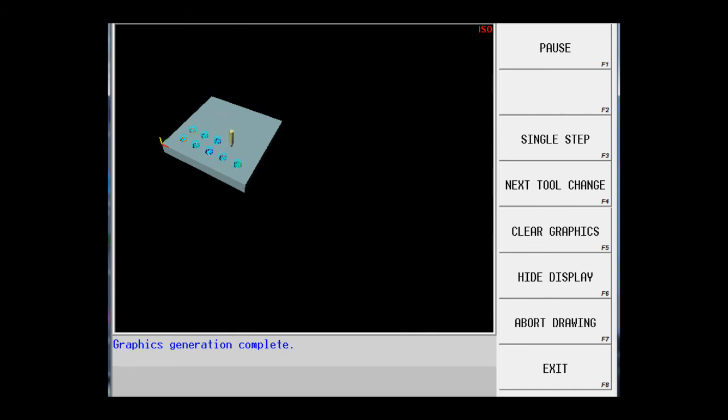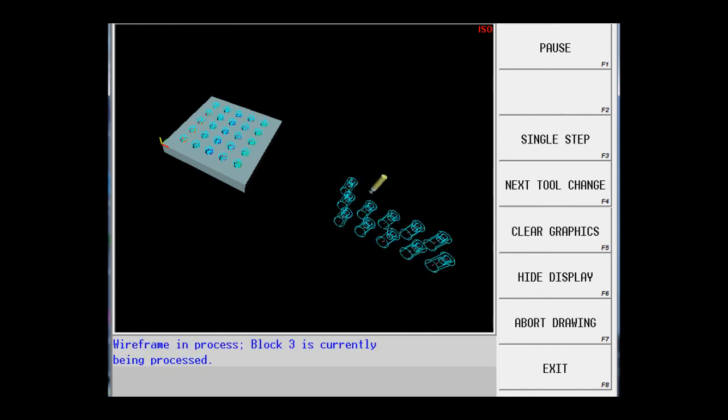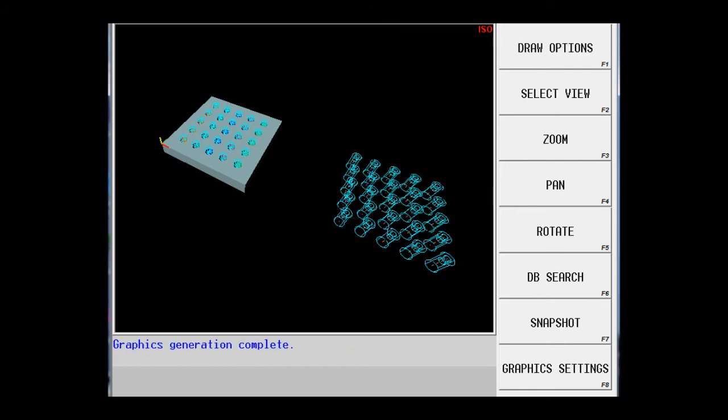I showed it to you in this manner only to show you that stock geometry does not pattern. There is no way for us to draw one small piece of stock and have that pattern with the geometry. So in this case, anything that was off of the solid model itself, when we were set to show solids only, wasn't displayed.